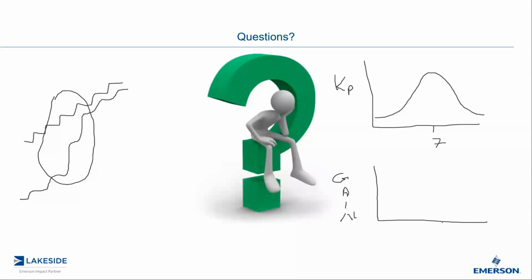And typically, again, with pH 7 here, my gain would do the inverse of this and come back up like that. So as my process becomes very sensitive here, I will decrease my gain there, and that will maintain overall stability over the wide operating range. Excellent question.